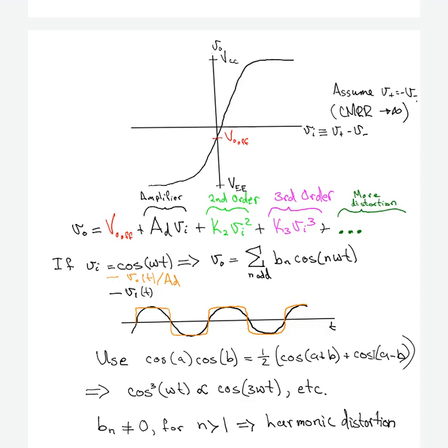Here we have another picture of something that happens because you're running this on DC power supplies that are limited. In general, the way the op-amp works is it can never put anything out bigger than the positive DC power supply or smaller than the negative DC power supply. An input-output curve you see here is somewhat typical. There will be, as we discussed before, a y-intercept of V output offset. And you can see that here in red.